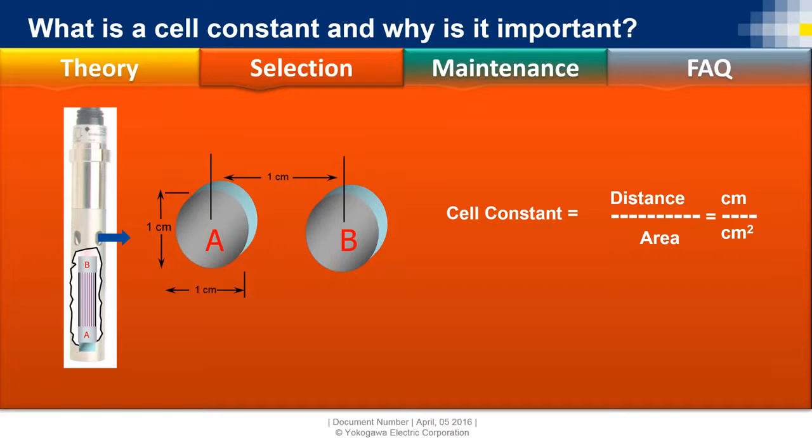That's what we do in low conductivity readings. We have a very short distance between the 2 measuring cells and we have a very large surface area, so that in a solution that has virtually no ions present, they have a large area in which they're more likely to be able to make contact with the measuring elements, so we're going to have better accuracy and higher measurement.